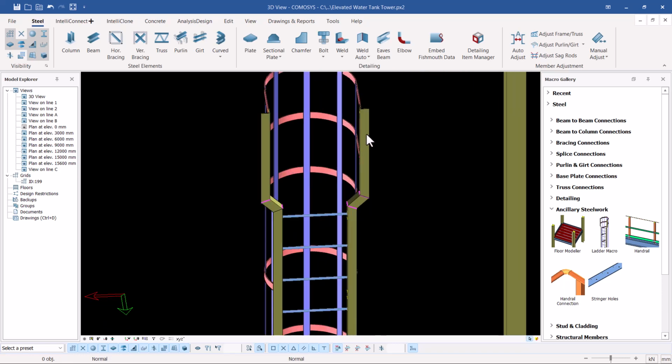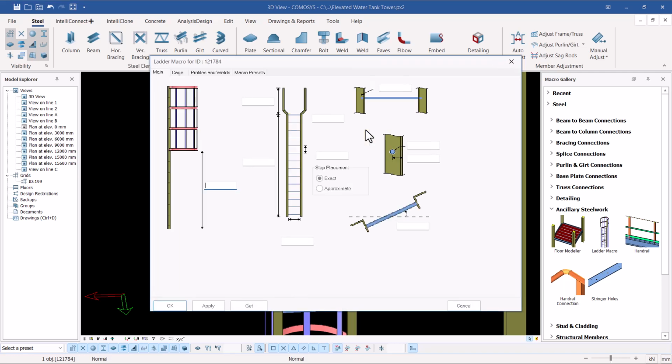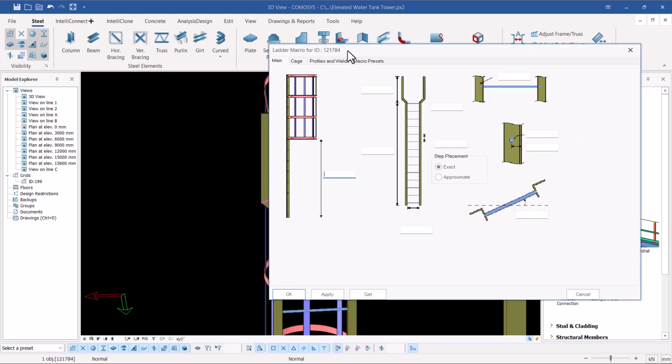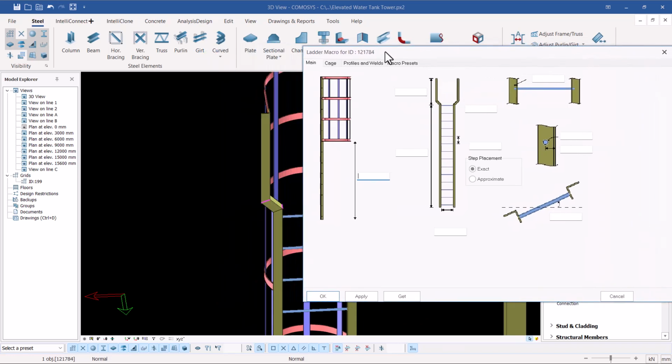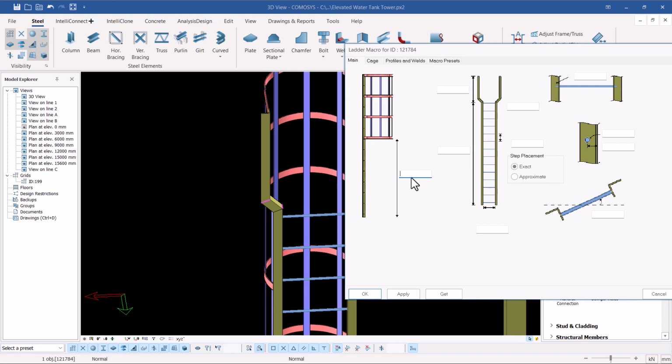To make more modifications, you just select any part of this particular component, then press the letter M on your keyboard, then press enter on your keyboard once again. That will bring up this editor dialog box here, for you to further customize this to match your measurements or your preferred design or your preferred height. And we have all this.